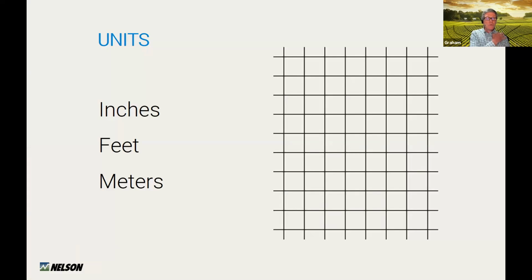One last thing before we go into IRRICAD and look at some different methods: it's worthwhile paying attention to units. Some importation processes bring units with the data. Some importation processes are unitless, and you don't know the units. They just have coordinates of X and Y with elevation and Z. Often there are several steps prior to importation. It's important to check the end result.